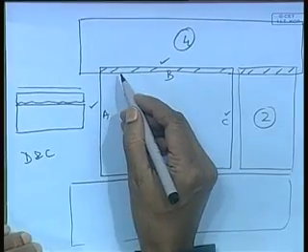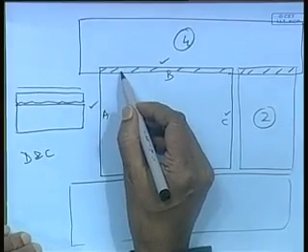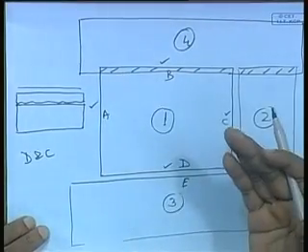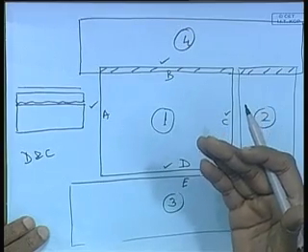But well, the objective should be there, so that I can maximize that and minimize this aspect of keeping green material, right. Because that is also another aspect. This green material, that means additional material I am keeping, how much to keep? 25 millimeter, 50 millimeter, 100 millimeter, 150 millimeter, it all matters.